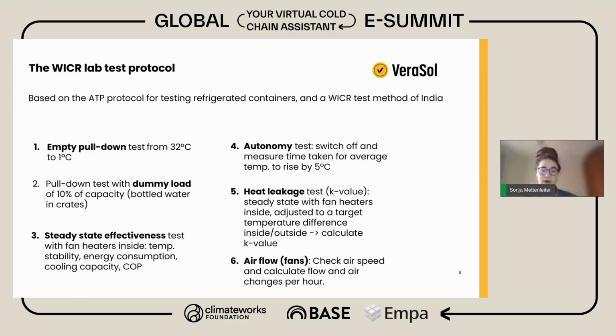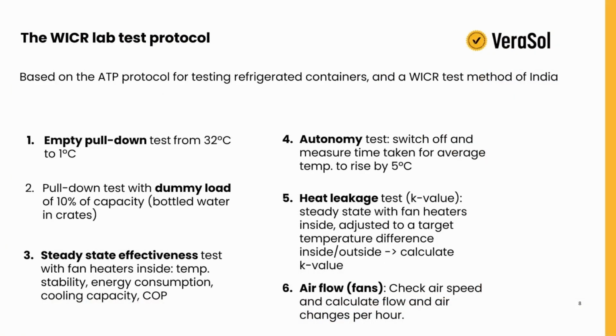Then the other thing, as I just said, it's not just about the spec sheets, but then also a lab test was developed, and it's based on the ATP test protocol for refrigerated containers, and a test method from India. In that, the tests conducted are an empty pull down test to see how fast the cold room can go from 32 degrees to 1 degree. Then we repeated that test with a dummy load, which is 10% of the total capacity, and the dummy load in our case is bottled water in crates to simulate a load.